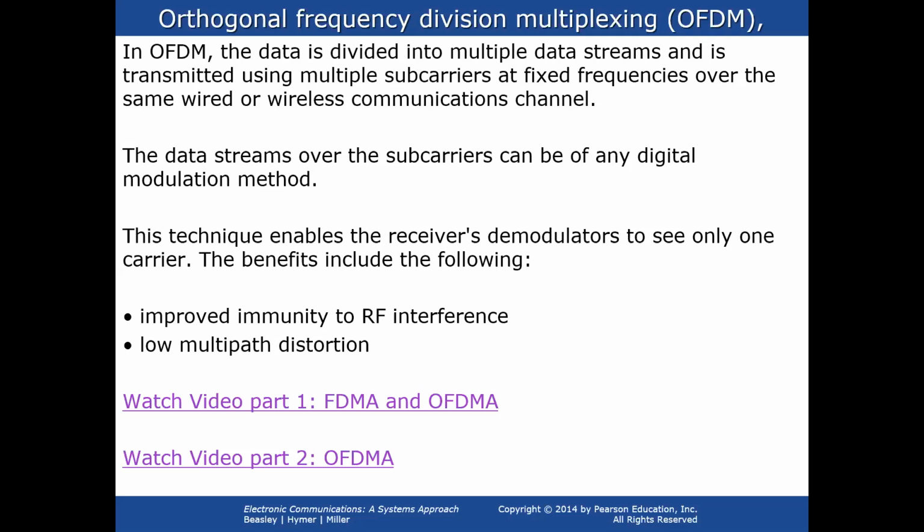Although there are many positives in OFDMA, the IFFT summation of multiple parallel subcarriers results in a high peak to average power ratio. High PAPR results in high power consumption for signal generation, but handheld devices have limited power capacity. This makes OFDMA unfavorable for uplink transmission. In order to overcome this, LTE uses SC-FDMA in the uplink direction.